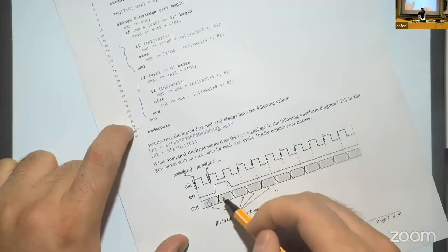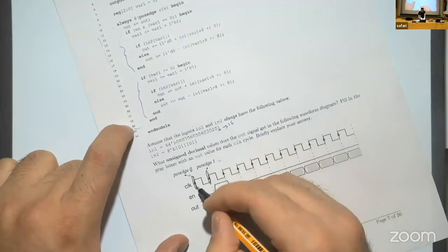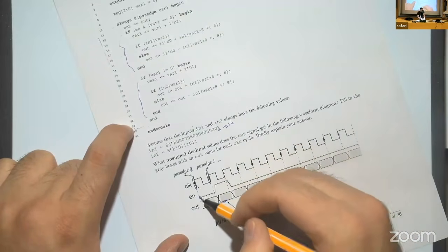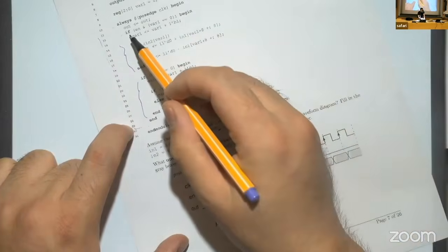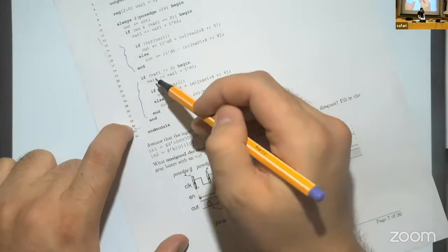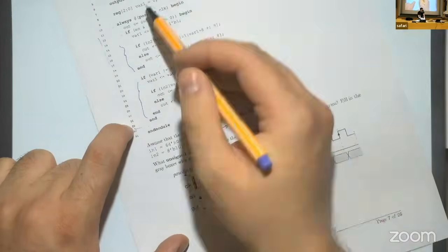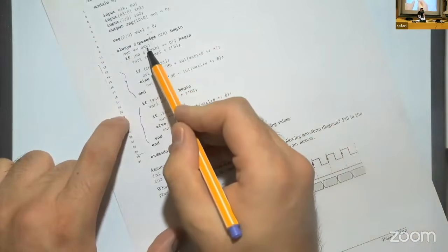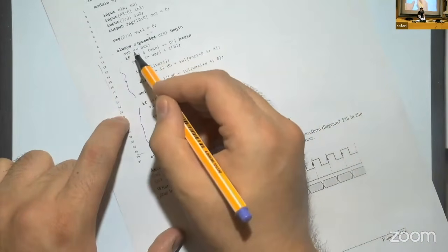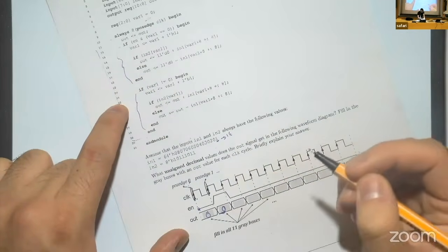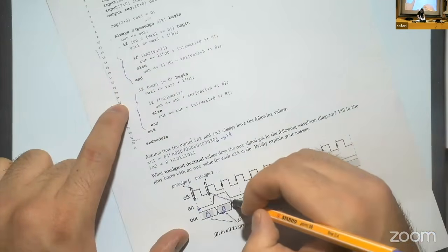Here, this out will be updated using this one. We see that enable is 0, right? So we go to this if clause, enable is 0. We cannot satisfy this one, and variable 1 is initially 1 here. That makes the output again have the same value as the previous one, which is 0. So this posedge clock 1 will affect this one.